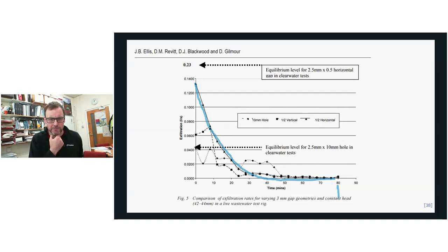So why is that? Why would that happen? It's because of the solids in the flow, particularly the toilet tissue. As toilet tissue goes through the pipe network, it breaks down, and when you're in the sewer it looks like a loose pulp that's just washing along the system. Things like wet wipes tend to hold together and they cause problems, but toilet tissue tends to break down quite quickly, as you can imagine.